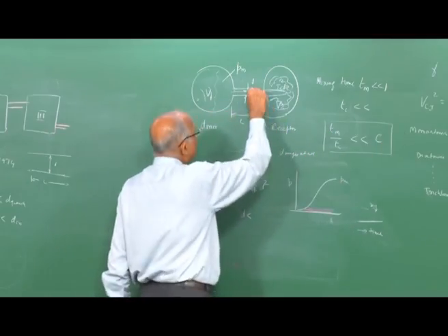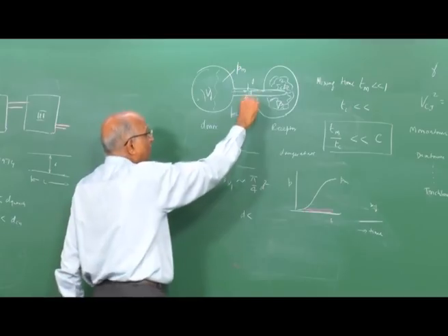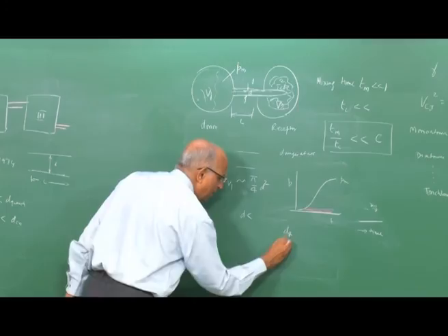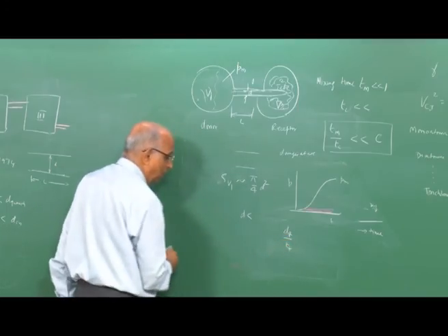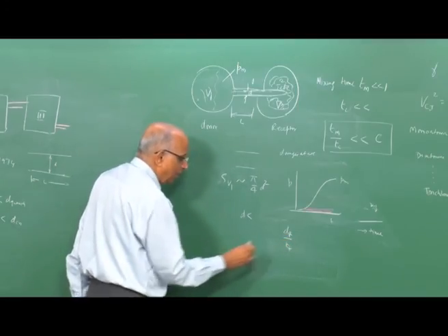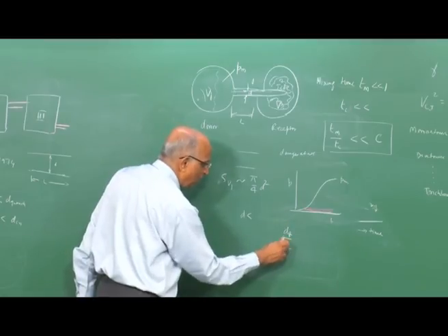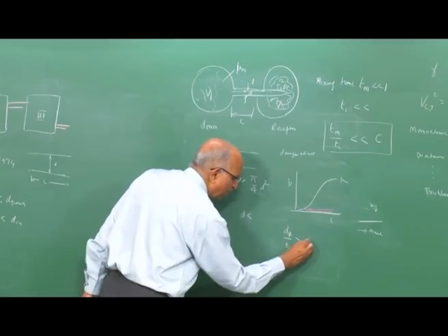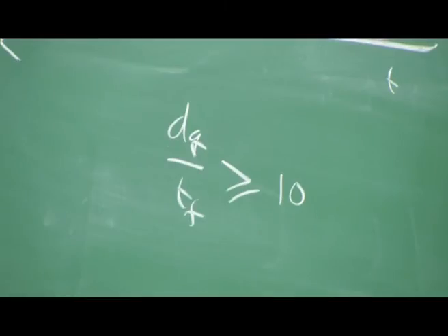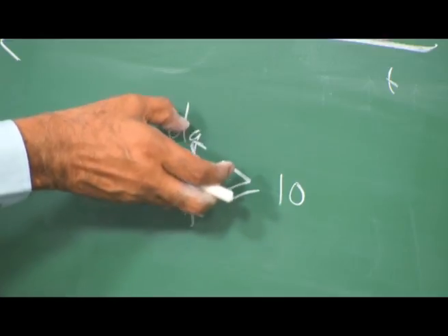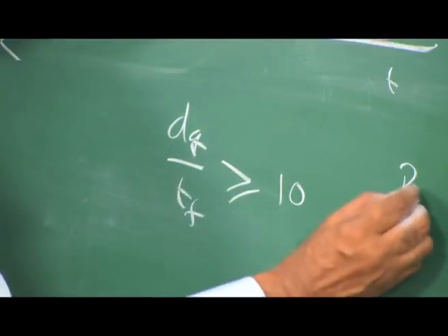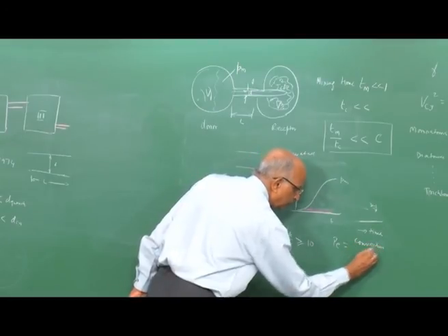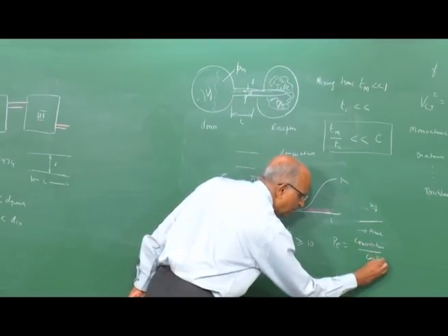It is not only the quenching distance, and mind you, whenever we do these things, we also talked in terms of quenching distance divided by the flame thickness or critical tube diameter for a detonation. Let's concentrate on flame dq by Tf. We said it is of the order of something like 5 or 10 or something of this order. We were also able to put the quenching diameter in terms of a Peclet number, that means the convection heat transfer divided by the conduction heat transfer.